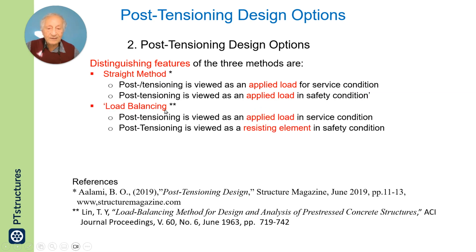In load balancing design, post-tensioning is viewed as an applied load in service condition, but as a resisting element in safety. In other words, in load balancing, for service condition, post-tensioning is a load, like dead load, live load. In safety condition, post-tensioning is a reinforcement, not a load. That is the difference between these two.